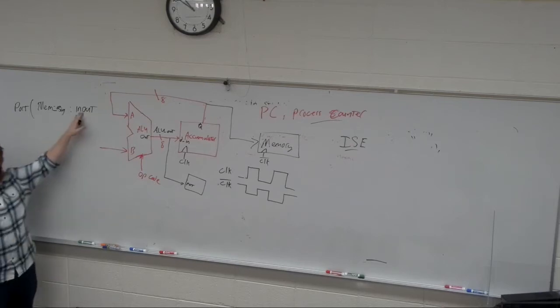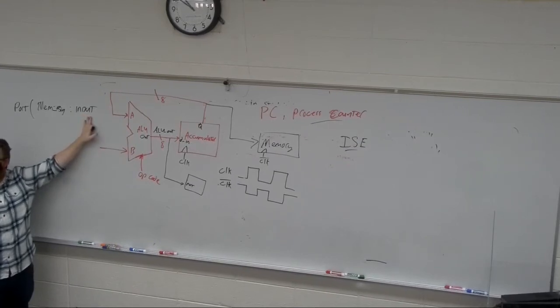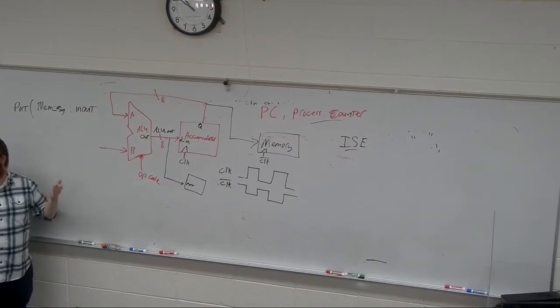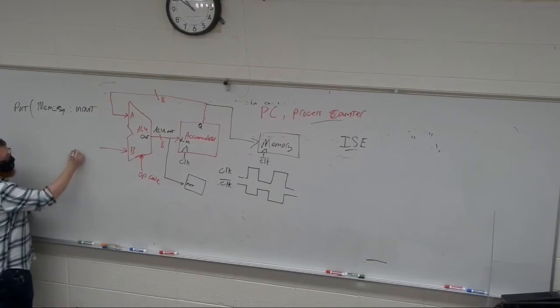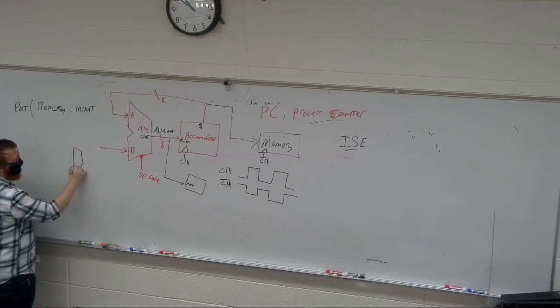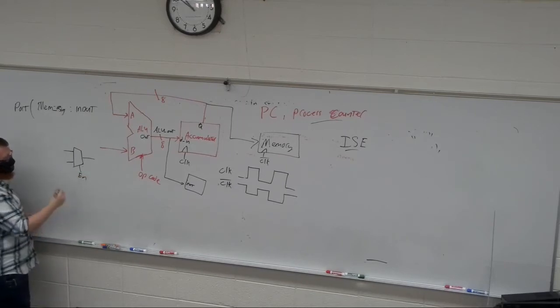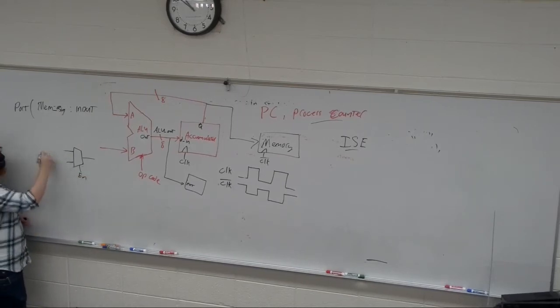Now, this can be a little tricky to deal with, because if it's functioning as an output, you just write to it. If it's functioning as an input and you're still writing to it, it can break things, right? Because if it's trying to write a 0 and receive a 1, then what is it? We don't know, problematic. So a good way of doing this is, let's build a mux. We'll call it enable. On 1, we'll have memory out.